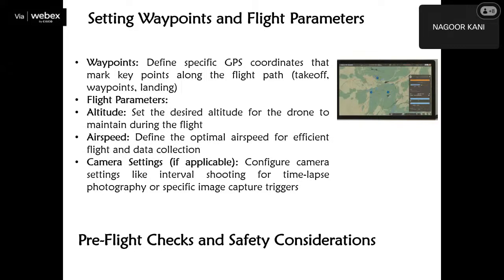We can do camera settings if required. That is a more advanced thing, in case you want to capture photographs at a slightly different angle, or plan a different resolution. Otherwise, if you give the overlap percentage, the resolution or GSD expected, or the flying height, it will automatically calculate airspeed, flying height, everything, even the waypoints it will create. So the software is very capable of doing that.